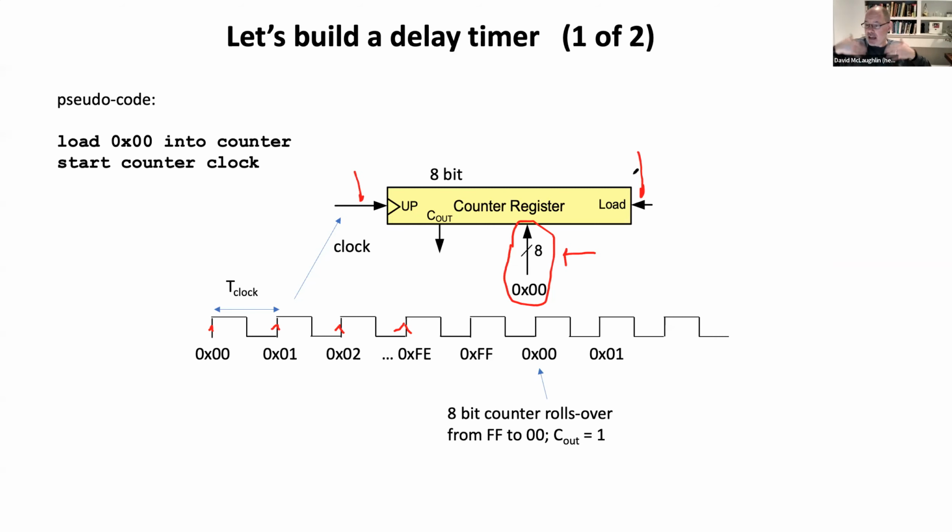But it often tells you it's going back to 0 by having an overflow, right? So as soon as it reaches 255 and rolls over back to 0 again, it has a bit that goes high that just says, hey, I had an overflow. So that's how this counter works. So in a sense, it's 9 bits. It's 8-bit for the count that we can preload, and then it also has this overflow bit so that you'll know that it has done an overflow, okay?